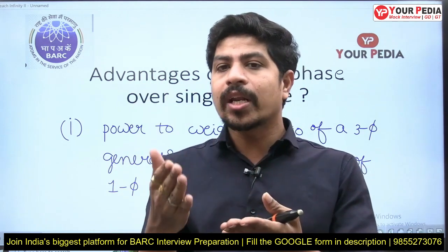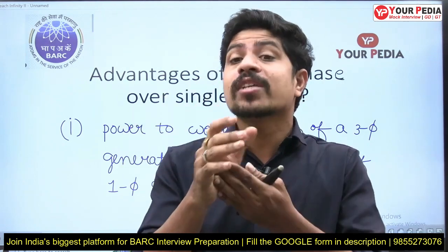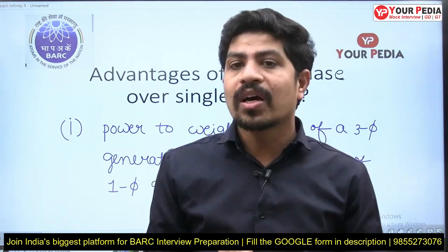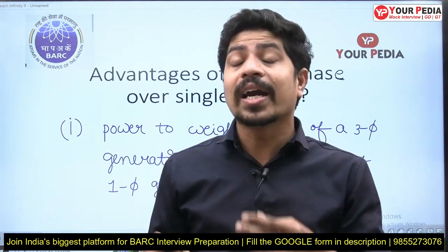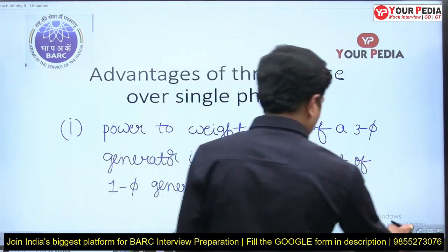So if you take power to weight ratio, both are delivering the same power, but in which case is more copper required? Single phase. Therefore the power to weight ratio of a three phase machine is greater when compared to a single phase machine. That is the very first advantage.